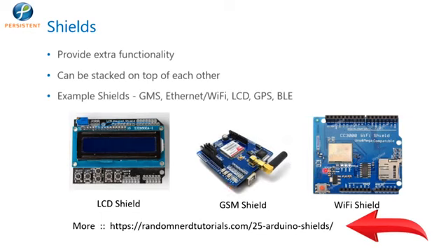As the original Arduino Uno board does not have inbuilt Wi-Fi capability, you have to have an external provision for it, and that can be achieved by putting this additional shield stacked on the top of your Arduino board. You may also think of a simple example here as the LCD shield. You stack this board on the Arduino board and any signals that can be captured here, you can have an LCD display.